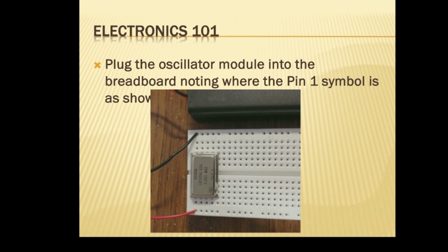Whoa. That's interesting. It's a 12 picofarad. Okay, so it's got a little too much capacitance there. It's sucking it to ground basically. But you can see it's starting to modify the waveform when we come out to here.